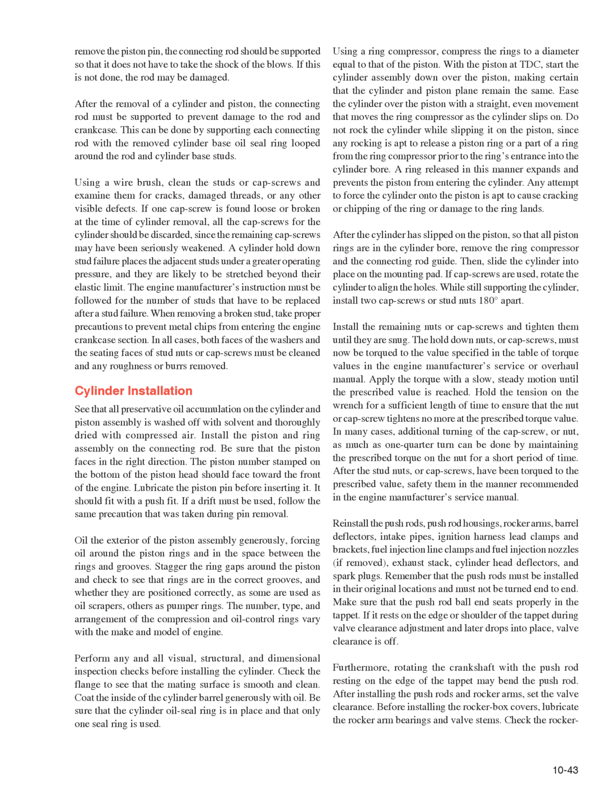The hold-down nuts, or cap screws, must now be torqued to the value specified in the table of torque values in the engine manufacturer's service or overhaul manual. Apply the torque with a slow, steady motion until the prescribed value is reached. Hold the tension on the wrench for a sufficient length of time to ensure that the nut or cap screw tightens no more at the prescribed torque value. In many cases, additional turning of the cap screw, or nut, as much as 1/4 turn can be done by maintaining the prescribed torque on the nut for a short period of time. After the stud nuts, or cap screws, have been torqued to the prescribed value, safety them in the manner recommended in the engine manufacturer's service manual.